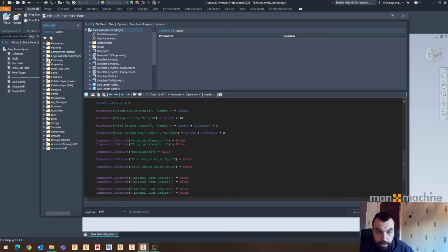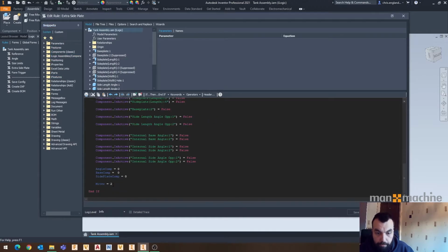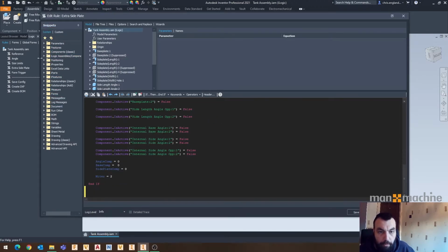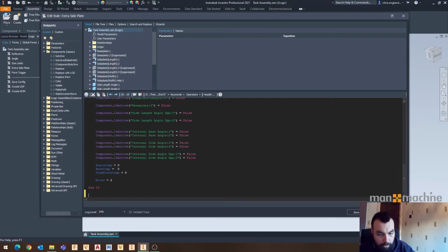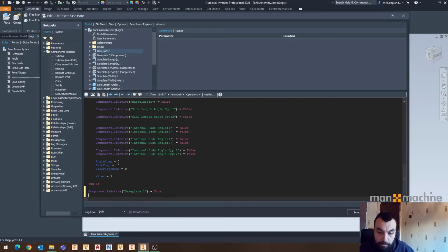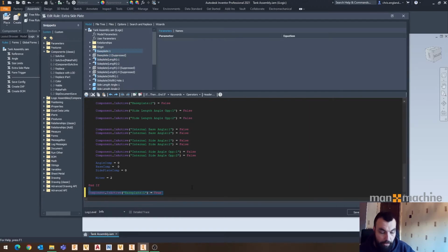And you can actually find that snippet if I just go down to the bottom here, and we can find it in components, classic is active. Double click on it, there's the part, and you just say equals true or false. Nice and easy. Another way to get to that point, although it tends to be a little messier sometimes, is to right click on, if you do it in a feature in a part, it comes out with all the features, parameters and such. But if you just right click and say current state is active, it brings out whether it's true currently or not.